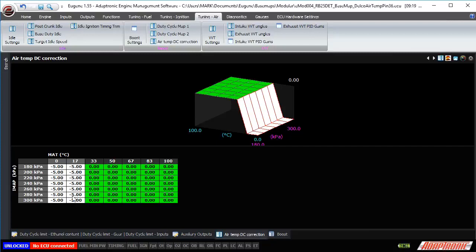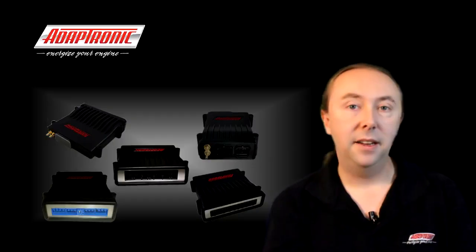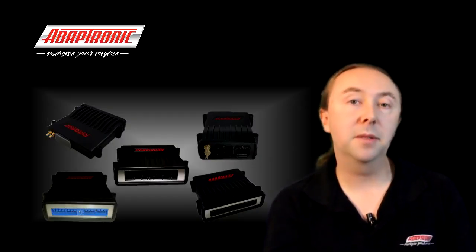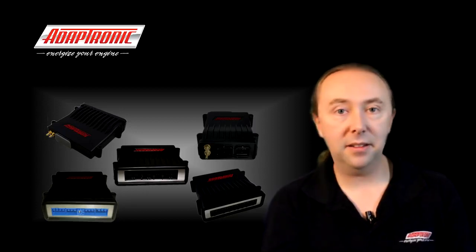Now, the vertical axis of this map is manifold pressure. So if you wanted to, you could actually use this as a semi-closed loop function if you like. I know that some tuners like to do this where they have a slight correction to the duty cycle based on the manifold pressure. The downside of this over using a proper closed loop system is, of course, that this map doesn't know where the target is or what you're trying to achieve. Now, mathematically, this is similar to a proportional controller, so it's still possible to make it hunt or oscillate if you make the ramp too aggressive.